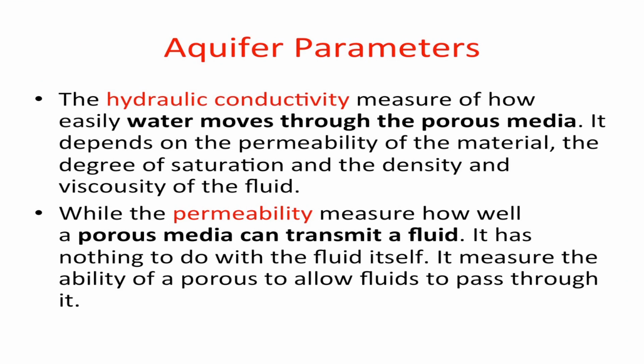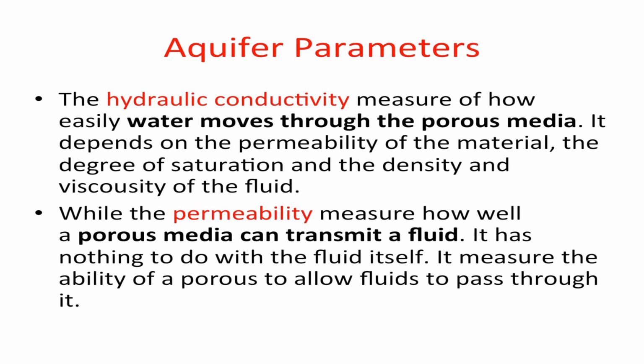Here we need to compare hydraulic conductivity and permeability. Both parameters discuss the ability of transmittance from one point to another point. Permeability deals with the property of the medium; it does not depend on the property of the fluid. Whereas hydraulic conductivity also explains the capacity to transmit water from one point to another, but it depends on the property of the medium as well as the property of the fluid, for example, fluid density, fluid viscosity, and fluid quality.